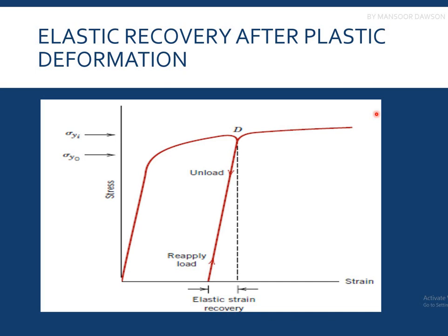So, elastic recovery after plastic deformation. Again, I'll be using that example of a rubber band, which I used previously. Let's suppose I have a rubber band of 3 centimeters, and I stretch it to 6 centimeters, and then I unstretch it, so it comes to 3.5 centimeters.